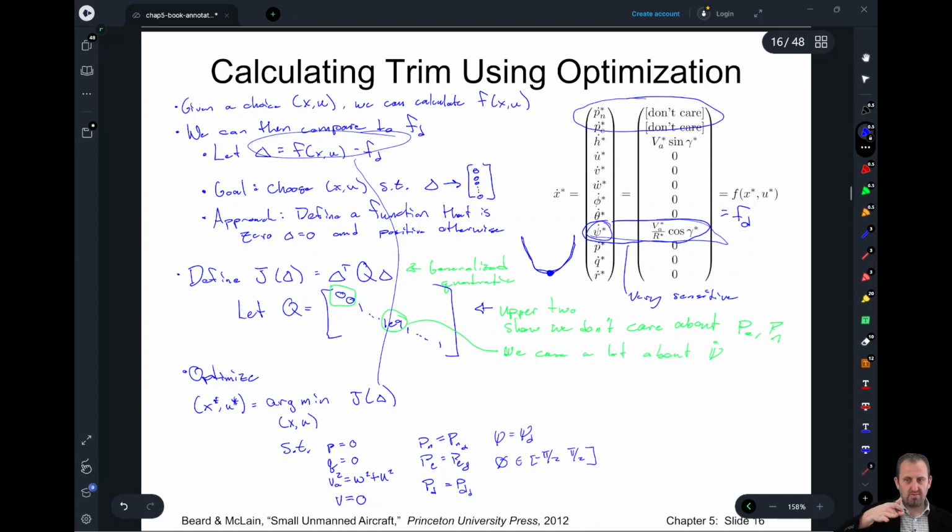So that would correspond to a bank angle all the way down, so we don't want to do any more than that. Theta is similar, we're going to be just a little bit more careful with theta and say that we can only go to pi halves minus some epsilon, some small value, just because once we go straight up, our dynamics have a singularity, which is problematic.